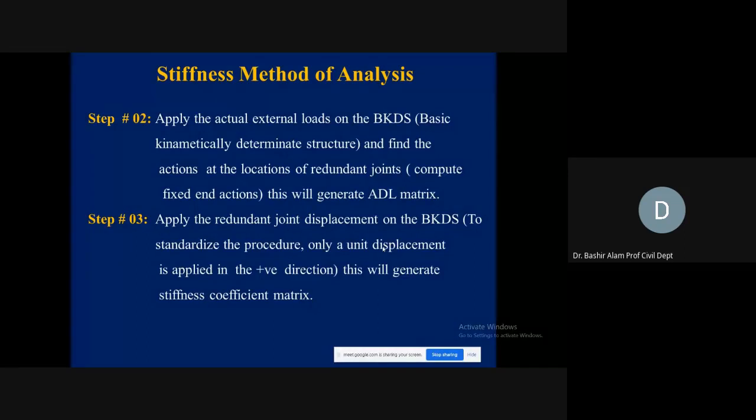Next, step number 2: apply the actual external loads on the basic kinematic determinate structure and find the actions at the location of redundant actions. Compute fixed end actions. This will generate the ADL matrix.